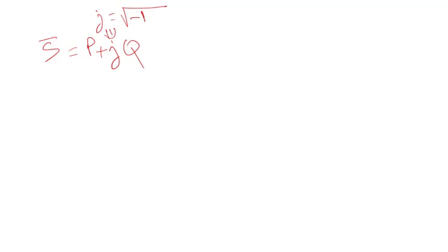There's equipment that has to be paid for, whether it's a capacitor bank, whether it's included in generation, SVC, StatCom, FACTS in general. Some equipment has to be installed in order to provide that reactive power. So instead, the correct terminology is reactive power. It's not imaginary. It's something that has to be there.